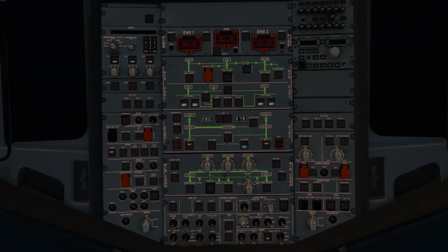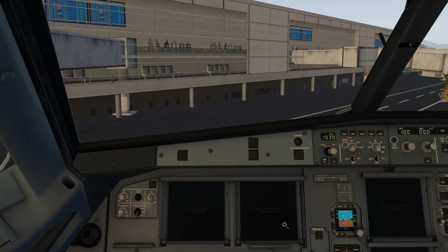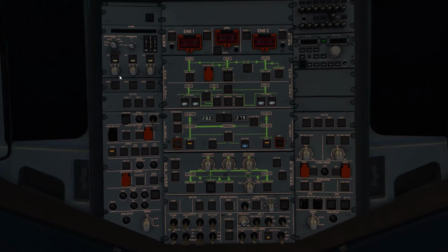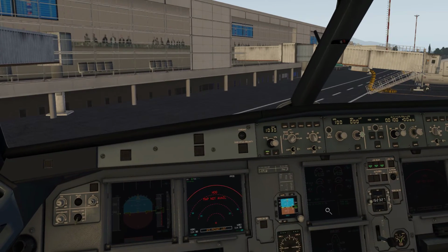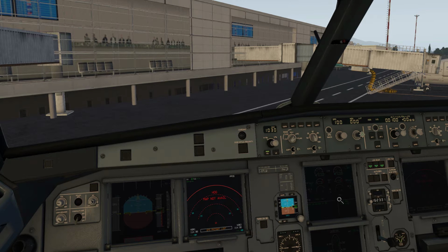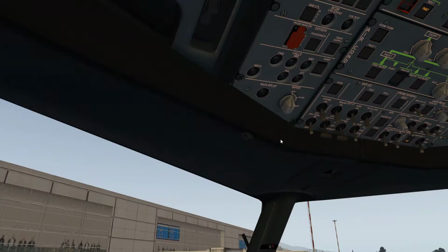This will just calibrate your position on the map, GPS wise, so that the system knows where you're at. And this will usually take a couple of minutes. Here you can see IRS aligning, over 7 minutes. So we definitely have to wait until the alignment is done before we move the plane at all, because if we move before the alignment is done, we have to start over again with the alignment at least.